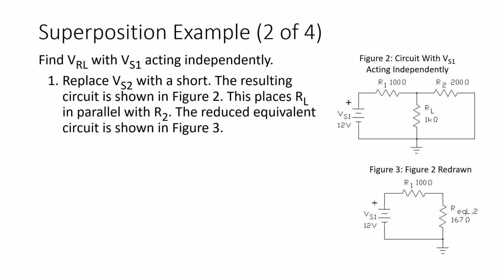So our resulting circuit places R2 and RL in parallel. And we've reduced the circuit of figure 2 to a simple series circuit by replacing RL in parallel with R2 with one equivalent resistance, shown as REQL2.